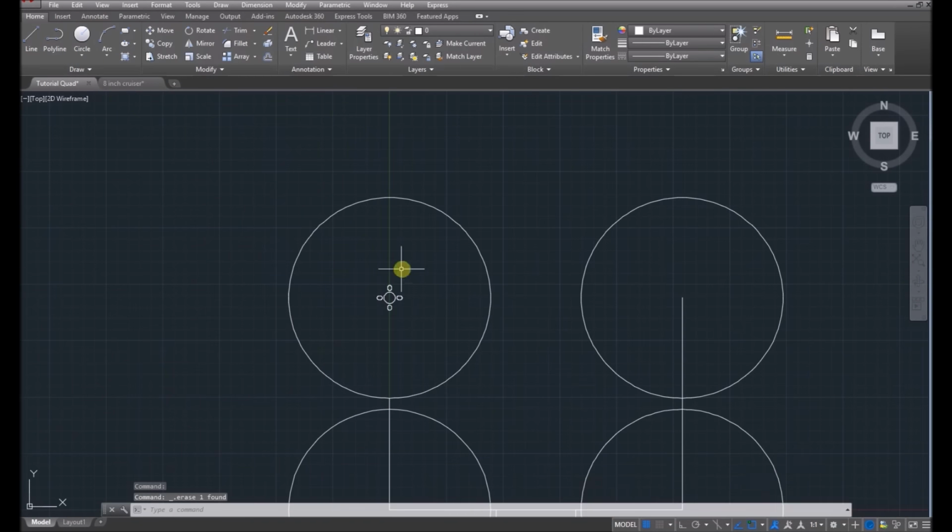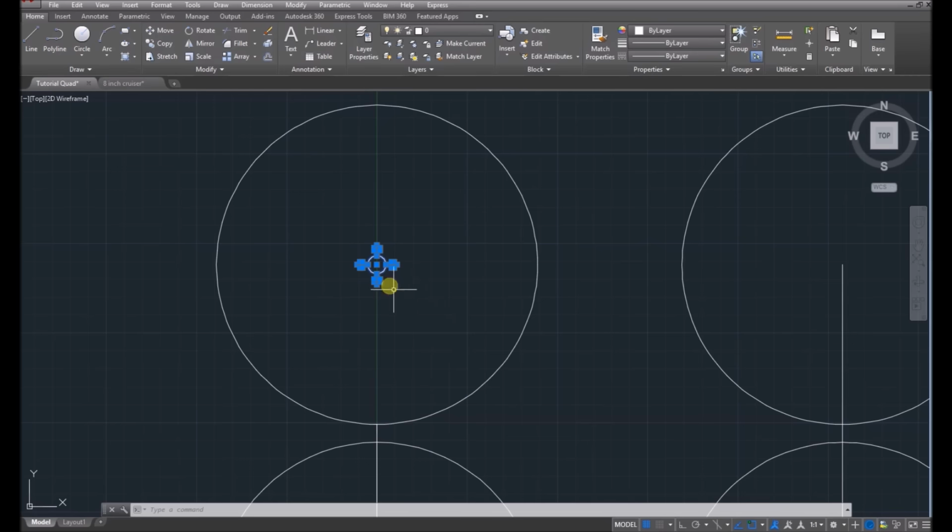Now at this point, because the cable is going to be coming out this side here, or out one of the sides, I'm actually going to use the rotate tool. So you select all your things, you click rotate, you click on that middle point that you want to rotate from, and then I'm just going to type 45 into my keyboard. So that's 45 degrees. So now we'll have the cable coming out this way.